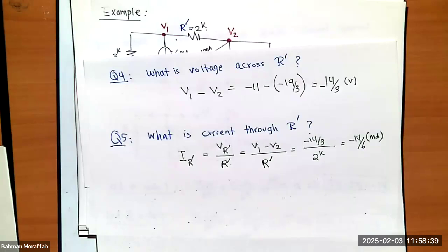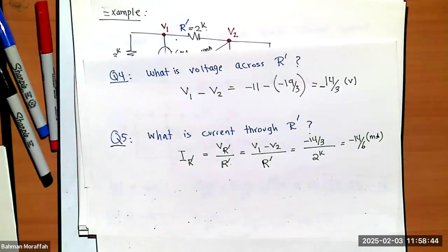Let's just have a quick review. There are two systematic ways to solve any circuit: nodal analysis and mesh analysis. Nodal analysis utilizes KCL and basically writes KCL for every single node that we have. What it produces is node voltages, even though we're writing KCLs.